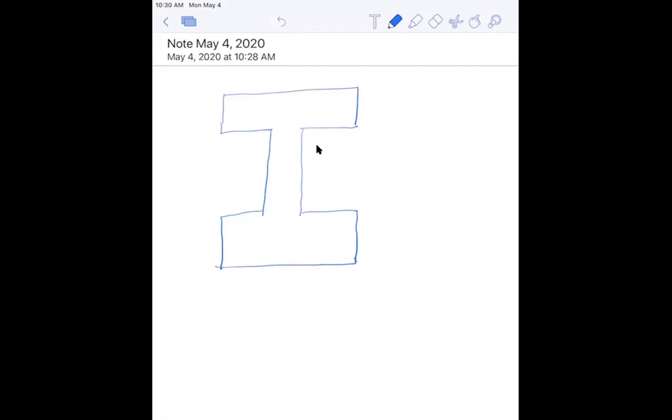So for the I_GT, gross moment of inertia transformed, we need to convert the steel, which is right here, and the compression zone. In the homework, this is the number 8 bars. We need to convert this to additional concrete. So it will be like this.